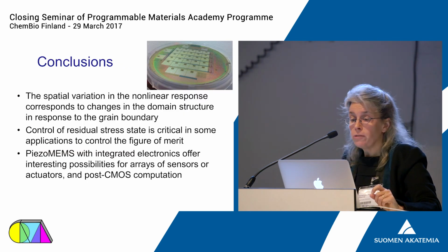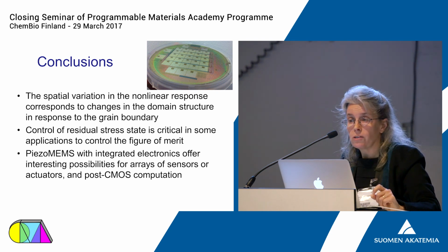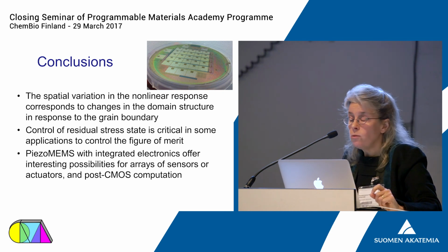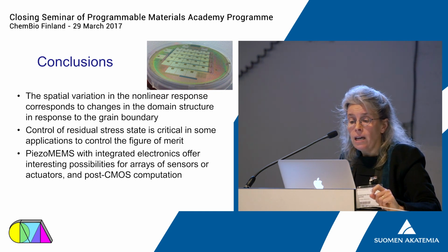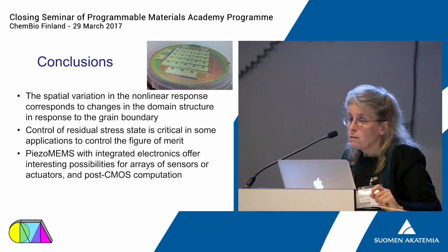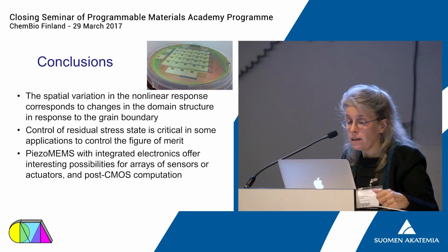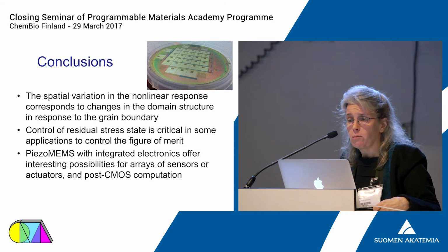So to conclude, hopefully what I've shown to you is that it is possible to utilize piezoelectric microelectromechanical systems for a number of applications. If you are able to control the domain state of that material, you can optimize materials for particular applications, and I showed you a particular example of that in the case of energy harvesting. And there's, I think, a lot of room to continue to move forward by being able to integrate these functional electromechanically active materials with electronics for array devices, or perhaps actually as electronics if we totally replace silicon as the transistor.